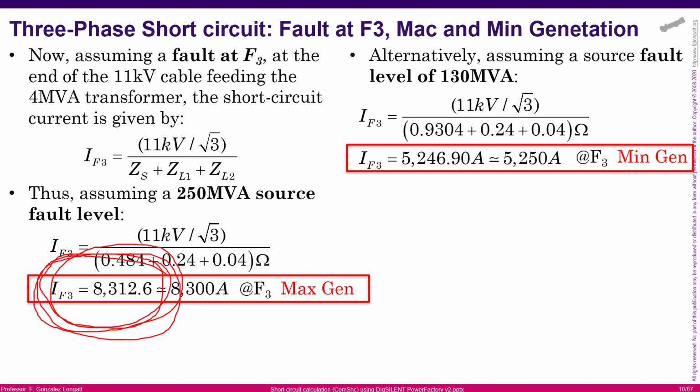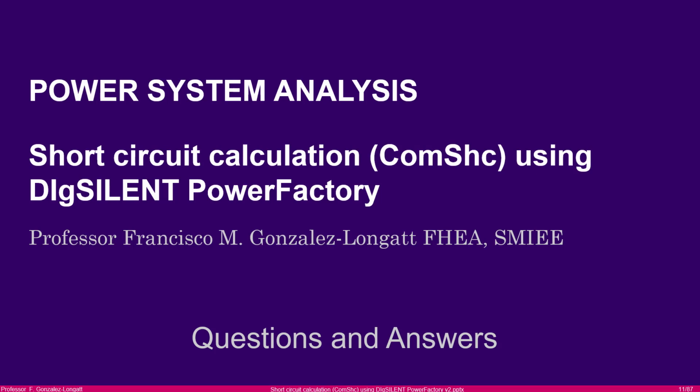At the moment I would like to say this is all for this short video. The idea was to make a short introduction about the short circuit analysis function and be able to demonstrate to my students that using the Thevenin equivalent model, using hand calculation, you can get the same results, and those results can be compared with PowerFactory. A lot of people say, why do I need to know the Thevenin method if we have a software that is doing the job?